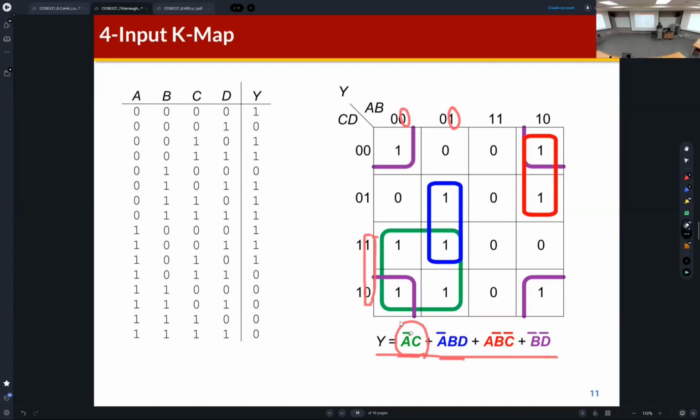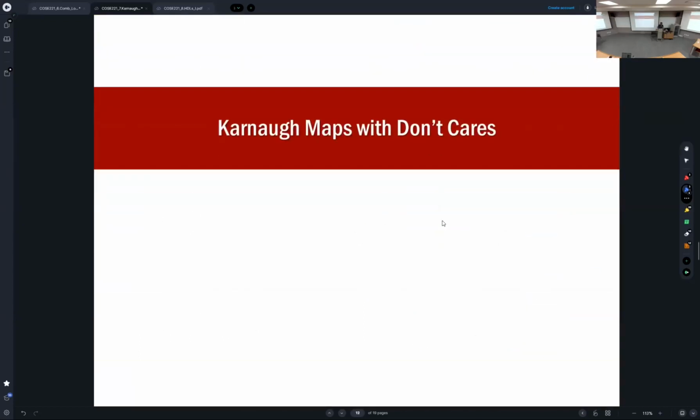Okay. So using the same way, we can define another prime implicant of this Boolean equation like this, B bar and D bar. Okay, understand? So the purple colored group represents B bar and D bar. Okay, this is the Karnaugh map.